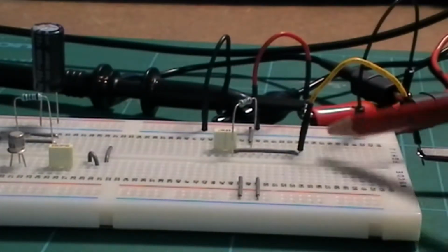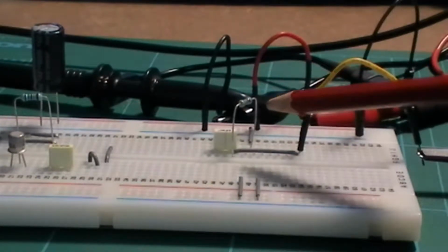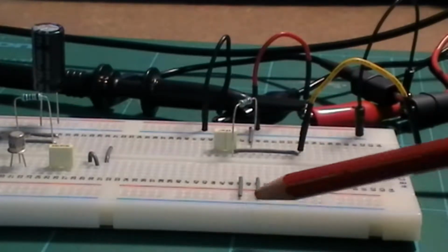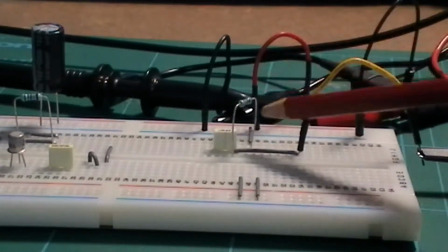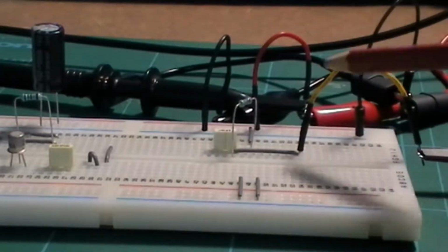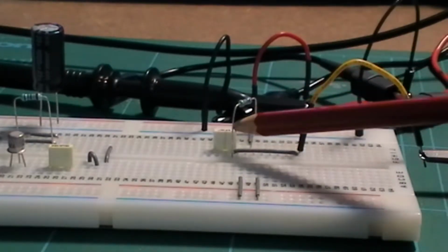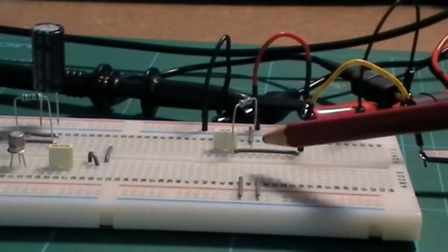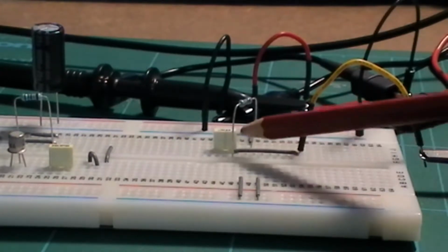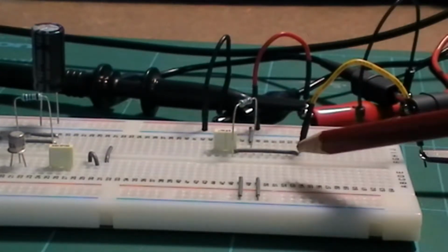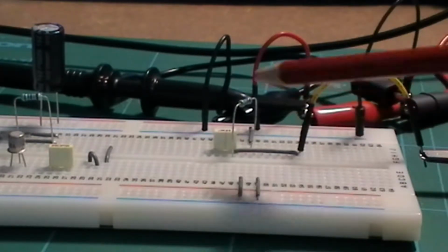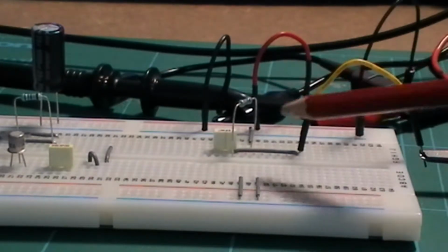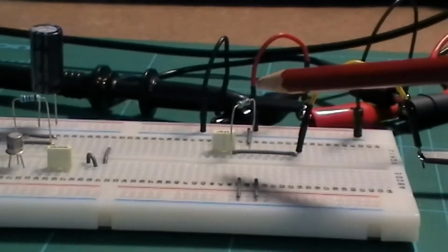Okay, so here we have on the breadboard my little setup. It's all very simple. Just a resistor capacitor. That's all we need for this. Signal comes in through the resistor, and that's my output for my signal, and then goes through the capacitor to ground. So very simple. Going to leave the 1K in all the time, so it's always going to be a 1K, but I will be changing that capacitor to see what I get. I've done some calculations as to what I'm expecting, so we'll find out if I'm right.